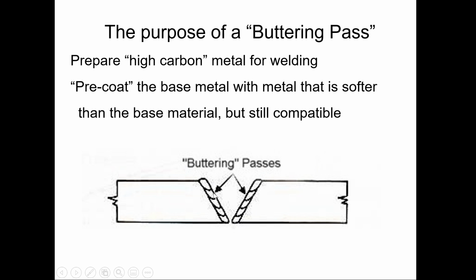Sometimes you get something broken. There's something referred to as a buttering pass, where we'll put a little bit of nickel on two pieces and bring them together, and then we bridge it with a little bit of nickel electrode. We make sure this is on here nice and safe, and then we go about this and we put on these buttering passes. This is a repair procedure if you get a die that's broken and we've got to get it working. The best thing is to actually make sure that we replace the part. Sometimes if we're stuck and we've got to put on a buttering pass, it's a very simple thing to do, and it makes it very nice to weld afterward. But you do have to respect your interpass temperature, because these layers, if you get all this too hot, will pull right off and start to curl towards you.